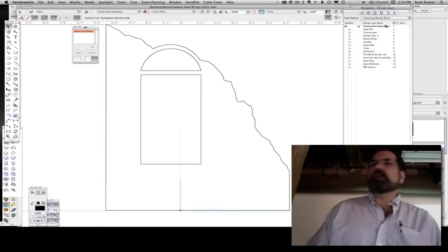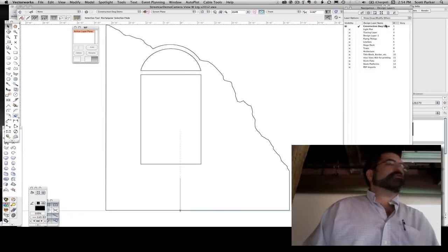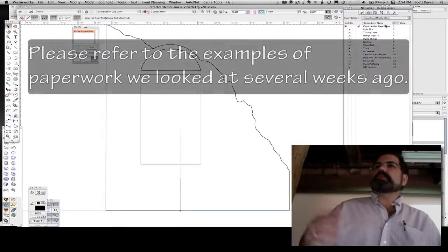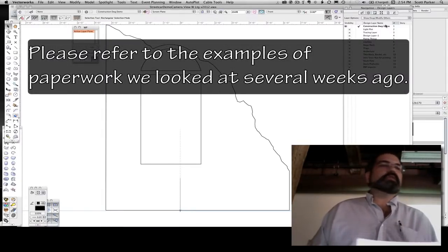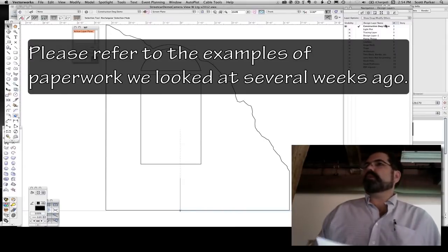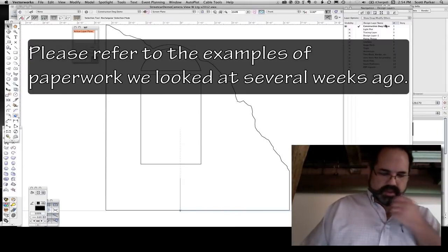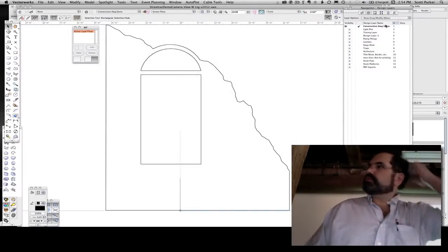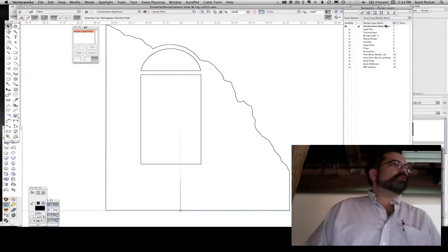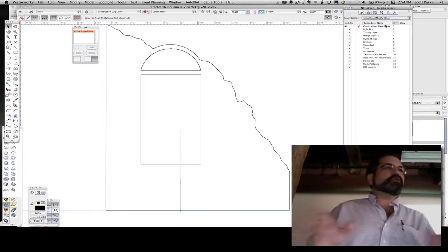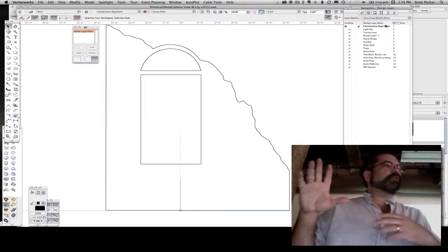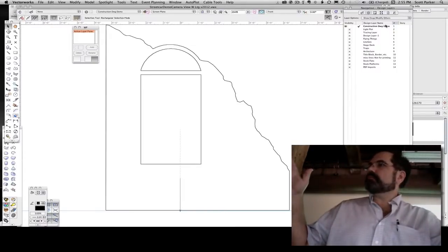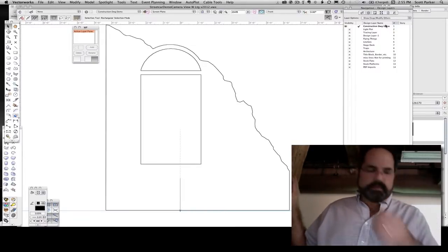The heaviest lines on a light plot, for example, are assigned to the lighting units, save for the architecture of the room, because that's an immovable object. So using the heaviest lines for the walls of the theater might be appropriate, but for the most part the lighting units are the most important thing. Your sheet layout. Frugal use of sheet space is important. Use the largest scale you can. We've chit-chatted about that. We want to have half-inch preferred, quarter-inch if the drawing is huge, but don't have a small scale leaving a lot of white space on the paper. Use the biggest scale you can fit on your paper.